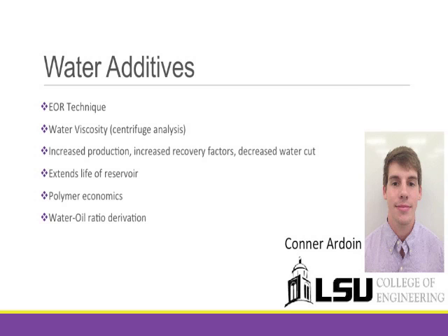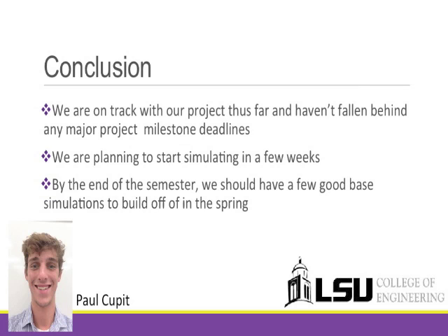I also plan on analyzing the effective change in the viscosity of the flowing fluids from the derivation of the reduced Buckley-Leverett fractional flow equation using the following assumptions. Gravity and capillary effects are negligible, pressures in the oil and water phases are the same, and viscosity ratio is some fixed value. In conclusion, we are on track with our